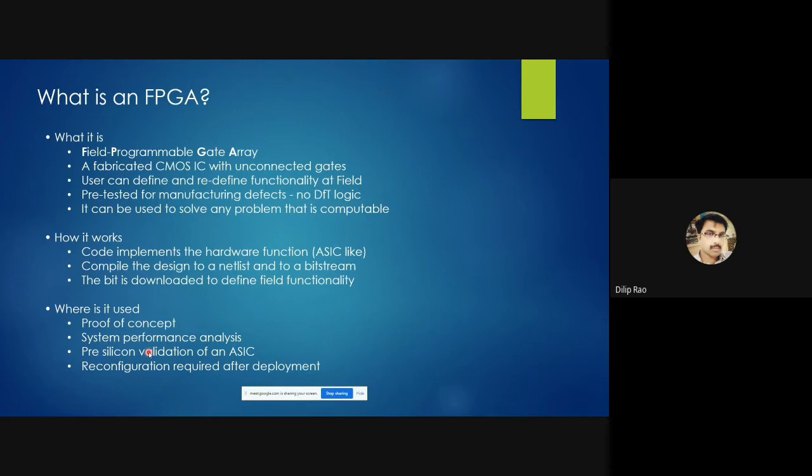So you implement the design on an FPGA, and then you validate from an IP point of view. If not, you don't have to validate every sub block, because those things are already done in the verification environment. At least from a system use case point of view, you need to validate that the expected system use cases are working as expected, and then you have the necessary confidence to go ahead for fabrication.